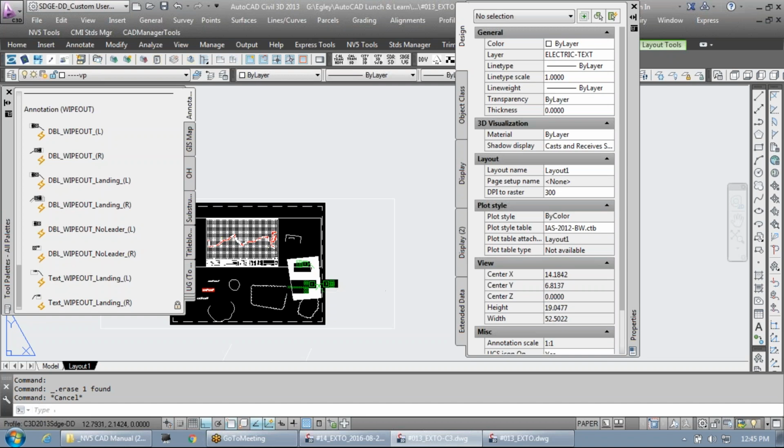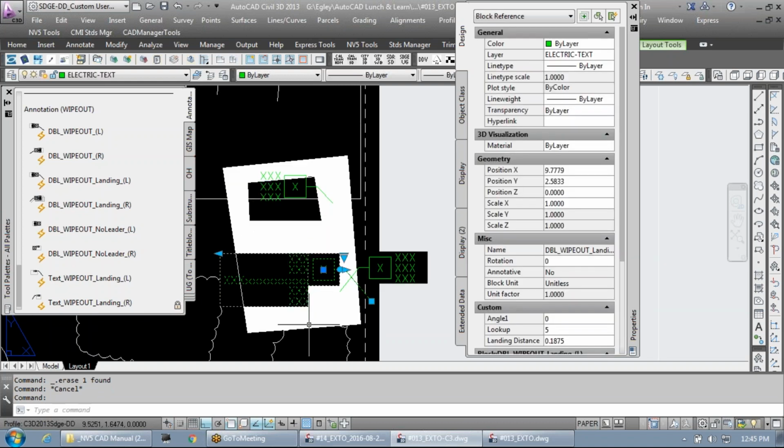Yeah. If you get into situations like this one, where you've got 2 lines of text, or 3 characters and then 20 characters, you don't necessarily want your wipeout to be wiping out that much. Maybe use the text mask for that one. Okay. Yeah. Or just explode the block.